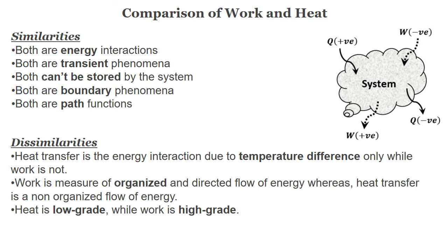Work is a measure of organized and directional flow of energy, whereas heat transfer is a non-organized flow of energy. The other dissimilarity is conversion of heat to work is less, whereas conversion of work to heat is more. Hence, we can say that heat is a low grade energy, whereas work is a high grade energy.